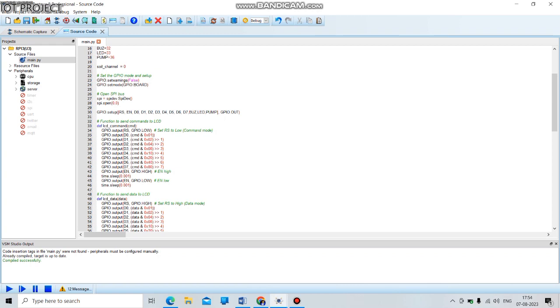Here we use a bitwise operation too, because when I mask the first bit, it will mask only that particular bit, and the bits after it stay as they are, with no change in the status of the remaining bits. Because I have to pass only one bit as an argument in this function, we use a bitwise operation. To mask the second bit we shift by one, then two, three, four, and seven, because here we have to mask the eighth bit.